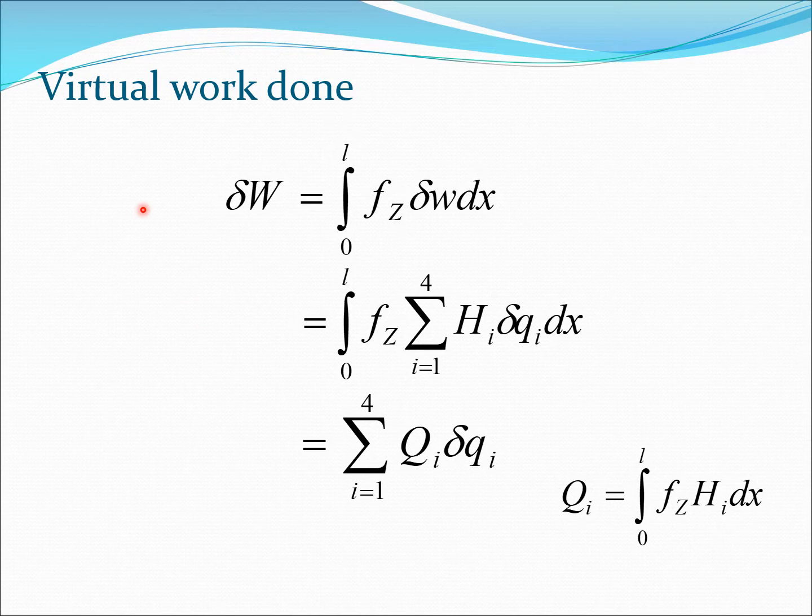Now before that, let us look at the virtual work done. So virtual work done would be the force into the virtual displacement, 0 to L. Now here again I put the summation that W is sigma i is 1 to 4 hiqi. So I get this equation here, and then I extract the integral term out. So I get Qi, which is the load vector or the force vector corresponding to this system.